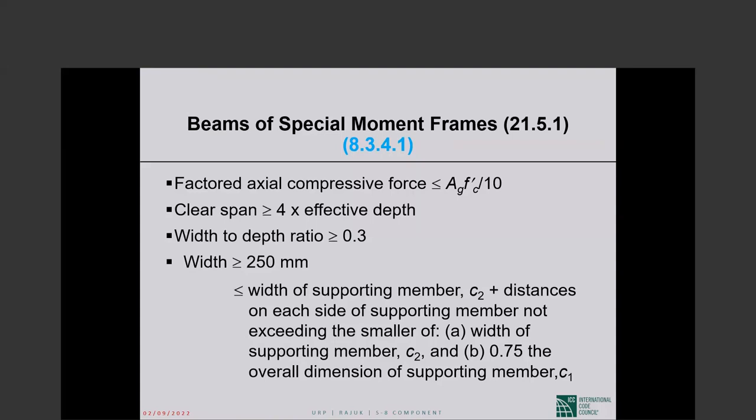In ACI handbooks, flat plate example, there is a minimum unbalanced moment, which is a function of dead load and live load at subsequent panels. That is used for punching shear calculation. But we don't see it in your slides.